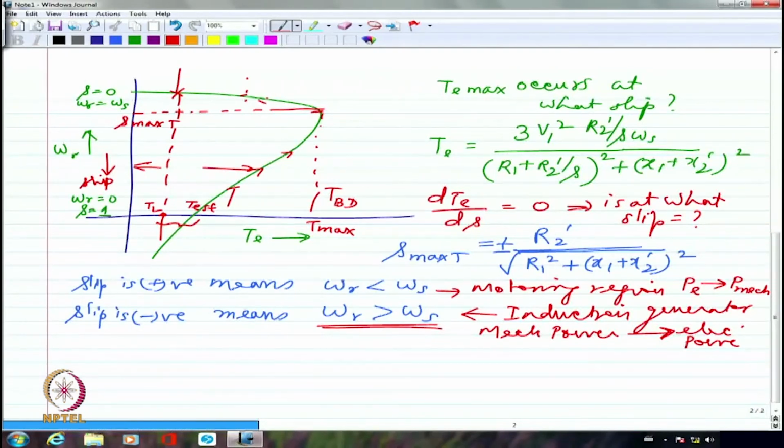And when it accelerates further, the torque is decreasing. So when it is not really feeding into itself, that is where stability is. Otherwise, there will not be stability. So the stability happens only in the linear region, not in the hyperbolic region. So wherever the stability is, it will come and settle there. So it will settle down at this point, which is probably P1. That is going to be the operating point.